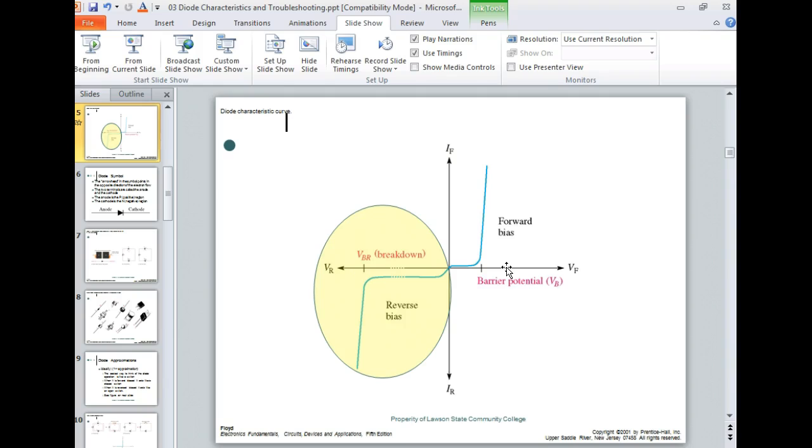So with semiconductors, we have to watch the temperature that we run those things at. Vacuum tubes didn't care. Them suckers ran. We heated them up to make them work. So vacuum tubes literally have to heat. But semiconductors, because of this reverse bias and this kind of stuff, they're rated at a temperature range. Usually it's pretty warm. It's about 70 degrees centigrade is the maximum they're rated at. But compared to other things like vacuum tubes, that's way, way down.